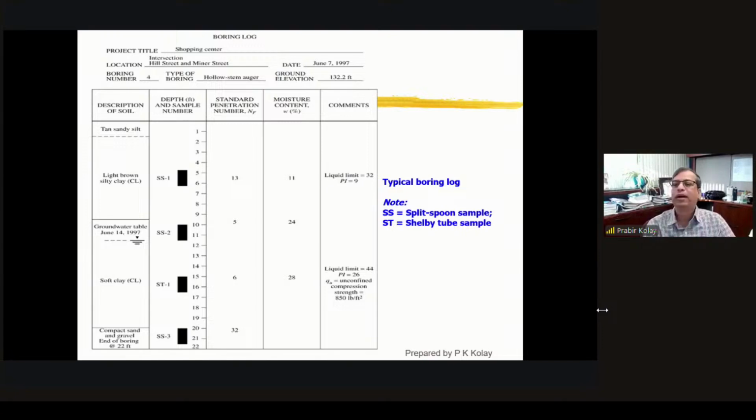Sometimes while taking this bore log, while incorporating the data in the bore log, most of the time we use the raw SPT number. So then we need to do the corrections. So I'm going to explain how to do the corrections. And then also we need to measure the moisture content or water content. And then also you need to write, okay, SS, what is the sample?